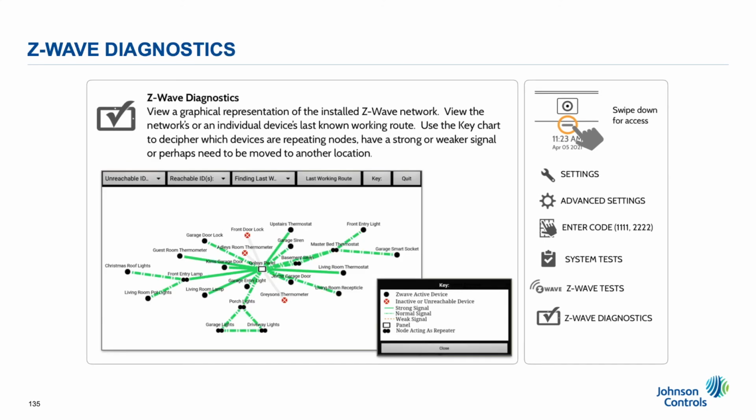Z-Wave diagnostics. This tool shows a graphical representation of the last working route of the Z-Wave network. To use this tool, first run a rediscovery, then second send a command to every device to control it: on, off, up, down, lock, unlock, etc.